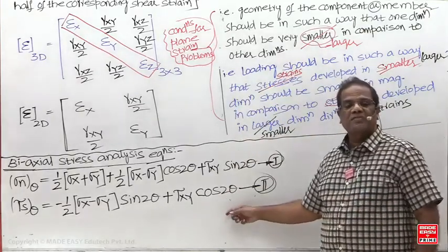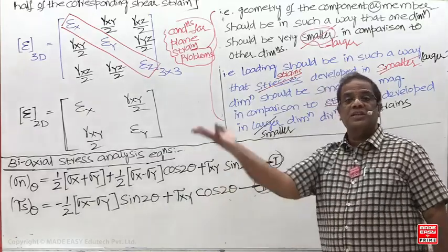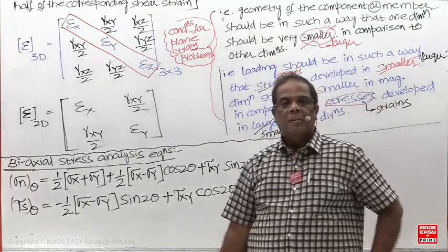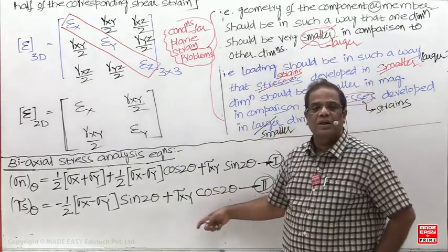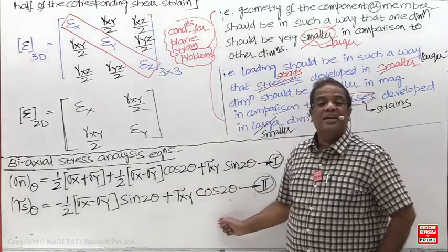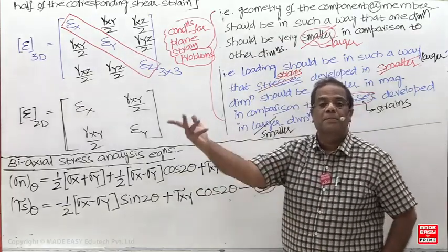Now what is the use of this equation? You can find out the shear stress on any plane by substituting theta. And what is the other use of this equation? If you equate this equation to 0, you are going to get a principal plane.